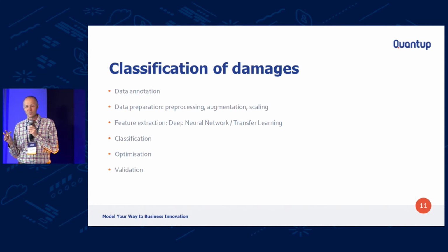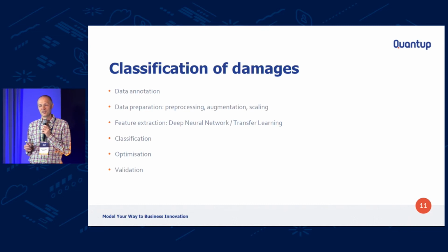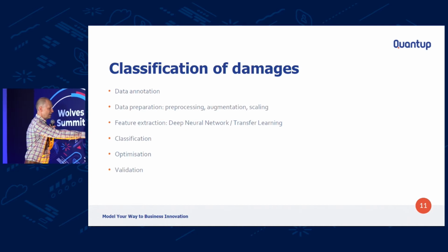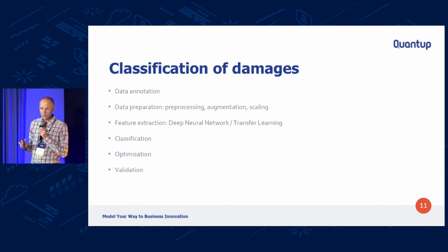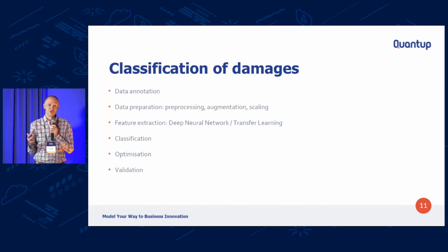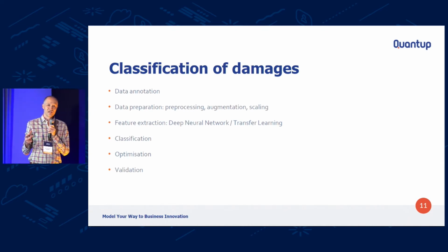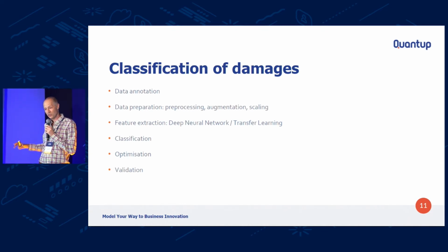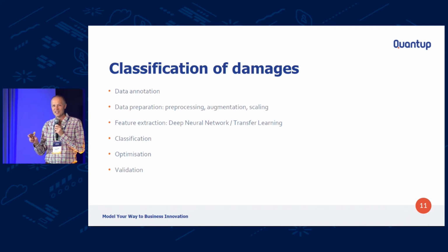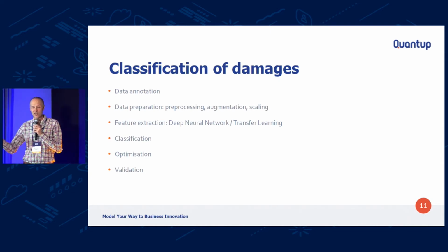The algorithm returned the probability of being damaged, and we needed to have cutoffs to decide if the probability given by the algorithm should be reported as damaged or not. So this step requires some multidimensional optimization. And what was very important was validation of the algorithm using additional data. For example, we teach our solution on one piece of track and check how it works on another piece of track or on another track.